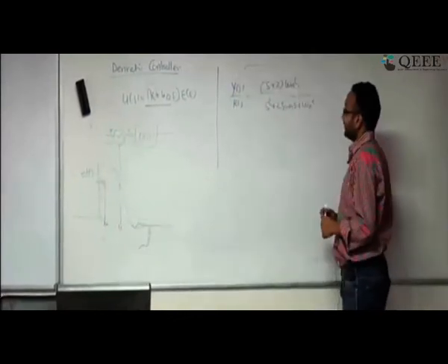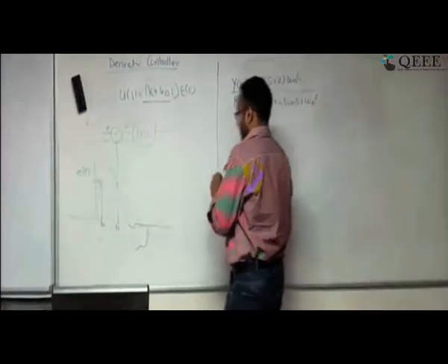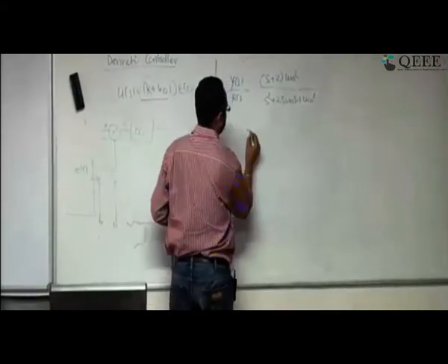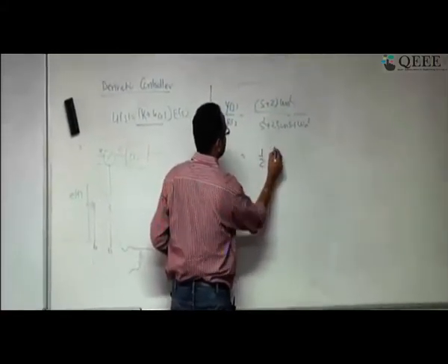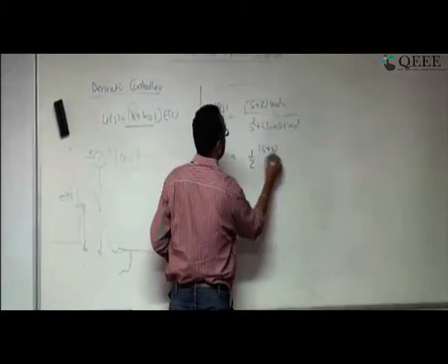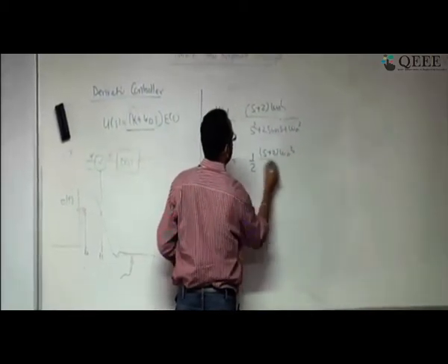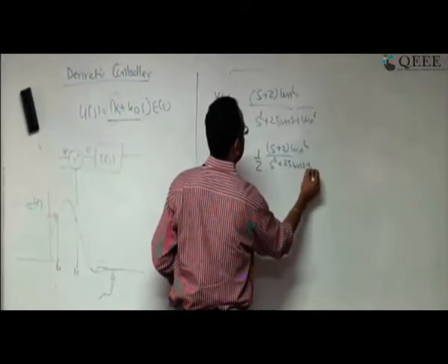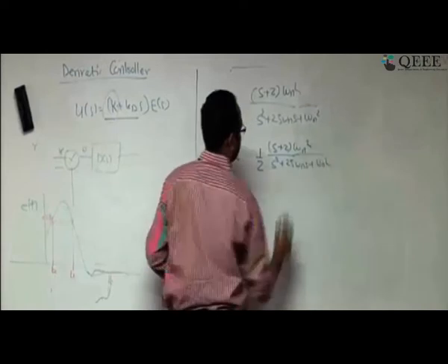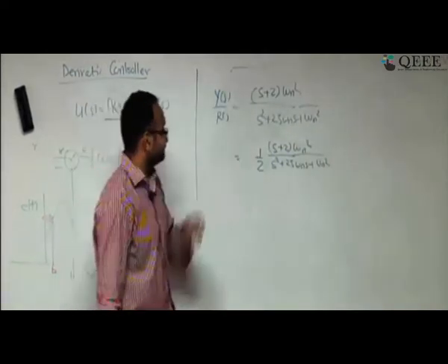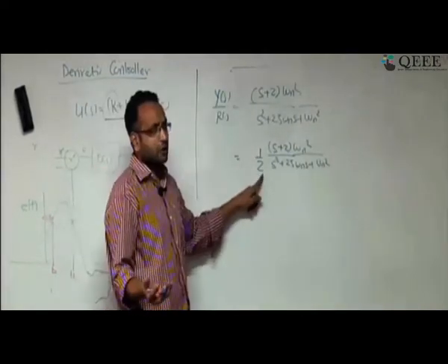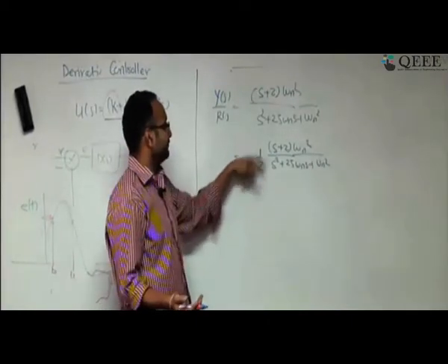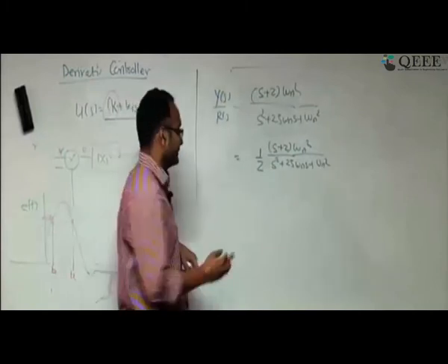This part is there. Now, a little bit of manipulation I will do to explain that. Let me add a 1 by z term: (s plus z) times ωn² over s² plus 2ζωn s plus ωn². Okay, this part is clear. This z I have added, z is some constant. You are adding a 0, so I am adding a constant, and this constant will affect only the steady state value. It won't affect anything else.